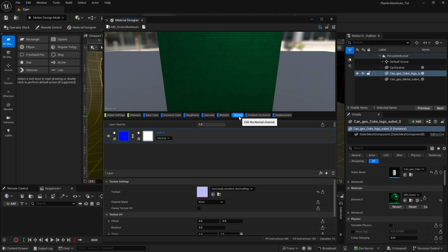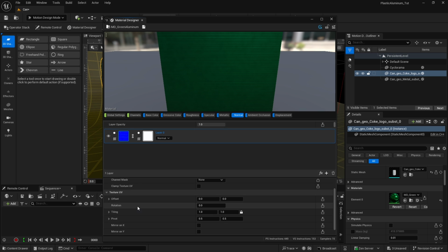And so in the normal map right there, we're going to go down to the UVs, and we'll drop down here and you'll see rotation. Very simple to do. We'll just set that to 90 degrees. So now they are moving vertical. We can save that out.